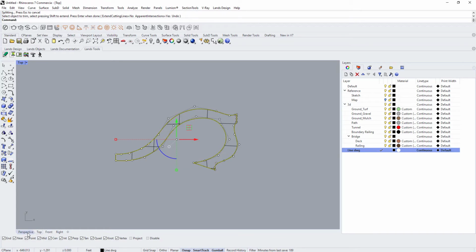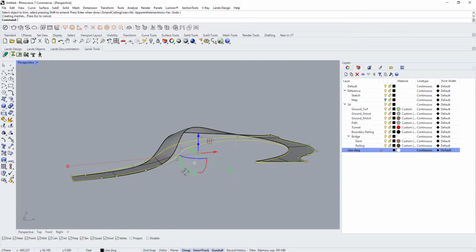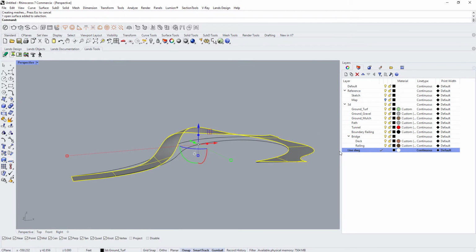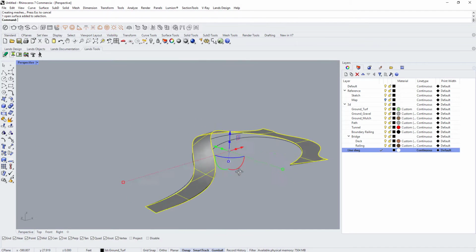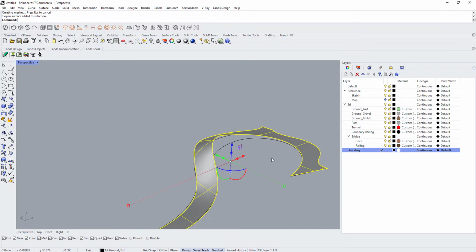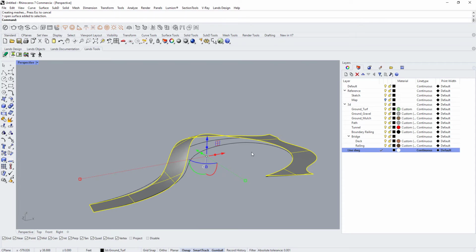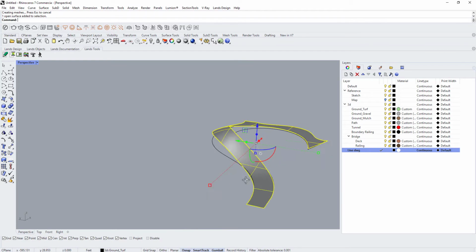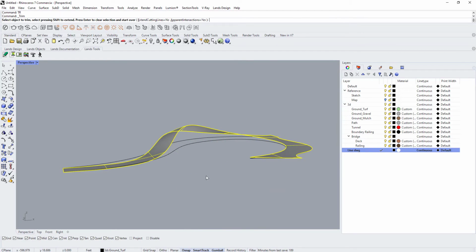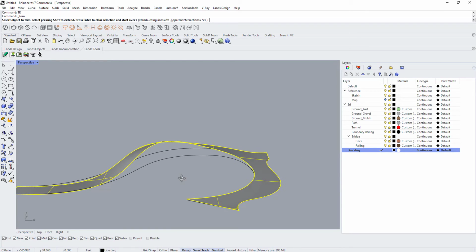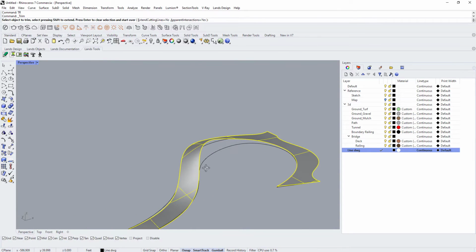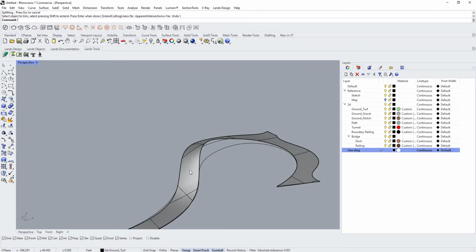So now you can see that we have this. This follows the ground plane exactly, but it has removed the other sides of the ground plane. So this is a very powerful command in Rhino that you can always work with 2D line drawings with the 3D shapes that you have created and trim or extend things simultaneously with 2D and 3D. So this is a pretty neat trick.